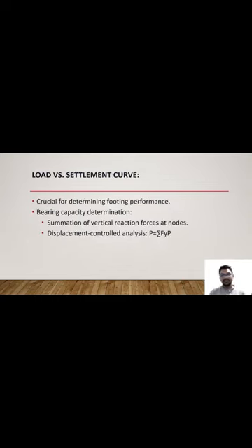For the load versus settlement curve, it's very crucial for determining footing performance, using the summation of vertical reaction forces at nodes and displacement control analysis, which is given by P equal to summation of F_i.